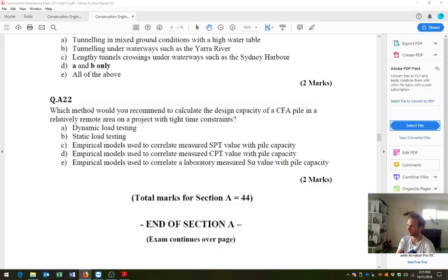That's Kevin's question. So we're up to Lawrence now. How can we improve pile capacity without changing design or risk factors? And the answer is pretty much in Kevin's post, which is testing. So we can improve our capacity, calculated capacity that is, through testing. The more we test, the more confident we are in their capacity, and hence the greater the Phi-G-B factor is, and hence the greater calculated capacity.